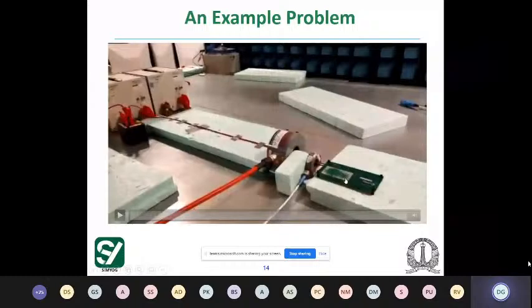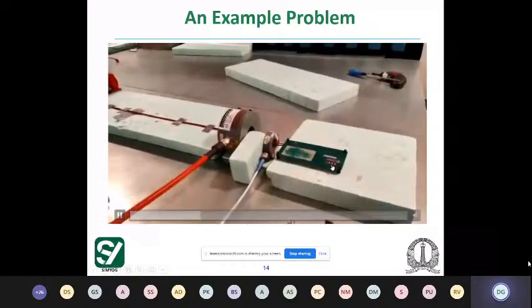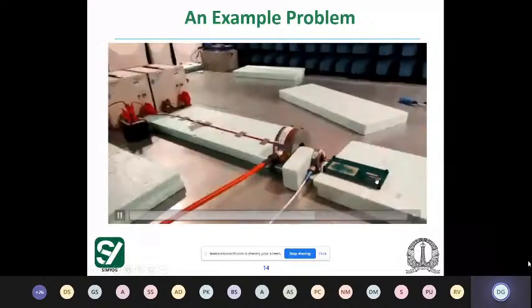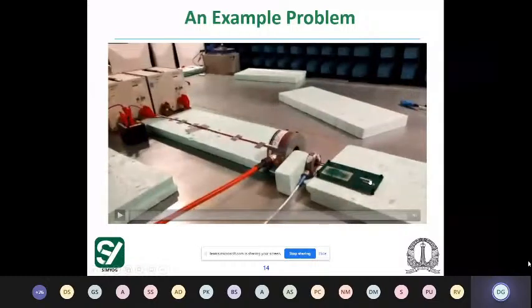What is happening in this stress test of this particular PCB is that you are injecting some noise onto the cable. This cable would be there in the system level design. You're injecting noise into this cable using an artificial clamp, and you can see that the LED is actually glowing, which means that there's nobody touching it, but the LED is glowing, which means it's a false touch. It's an EMC failure event, and that's what we are trying to work on. I'll tell you what we are trying to work on in just a little bit.